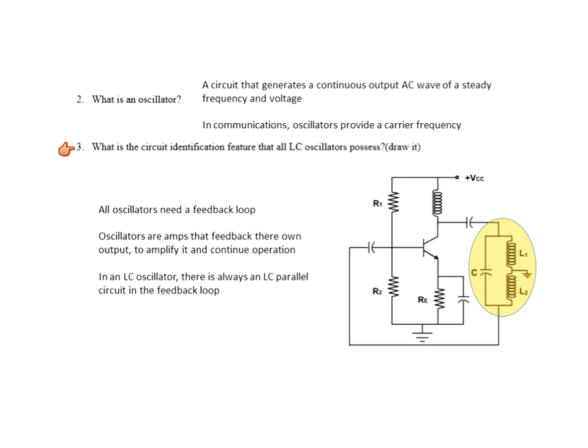Now, how do I normally identify an LC oscillator? Well, L and C means an inductive or capacitive oscillator. Inductive, capacitive. These are the frequency determining components. And you'll recall that in a Class C amplifier, the frequency of operation for an LC tuned circuit is equal to 1 over 2 pi square root LC. Remember that? 1 over 2 pi square root LC.